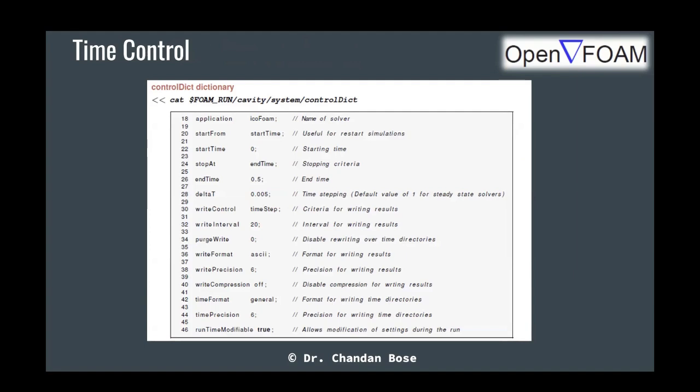So these are not the time step. This is exactly where you want to write the snapshots containing the field variables such as pressure and velocity for all your domains, all the coordinates or base points. For example, if you want to write the snapshot for each time step, your data will be huge even for a simple problem, and we don't need that.